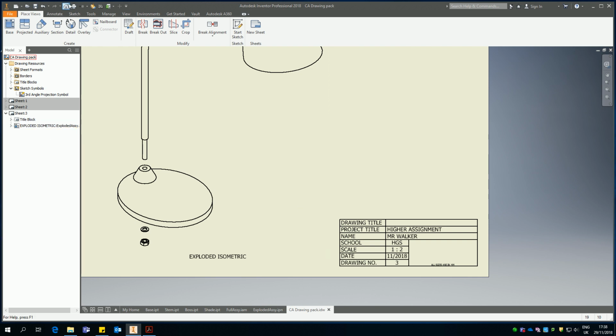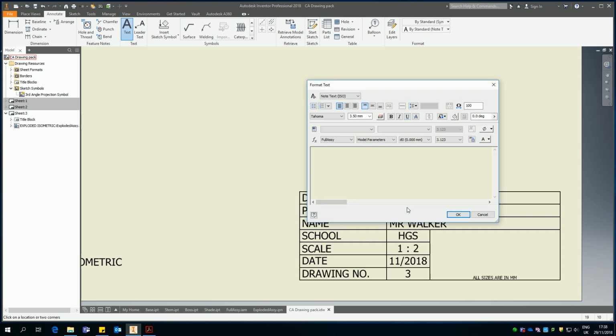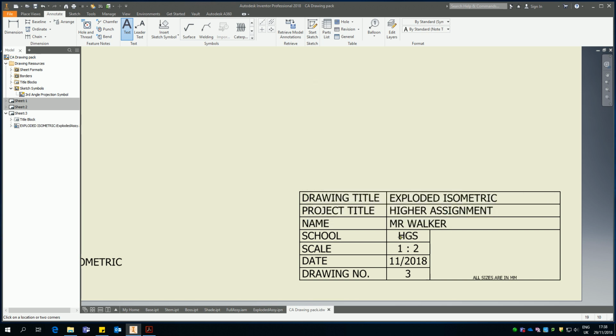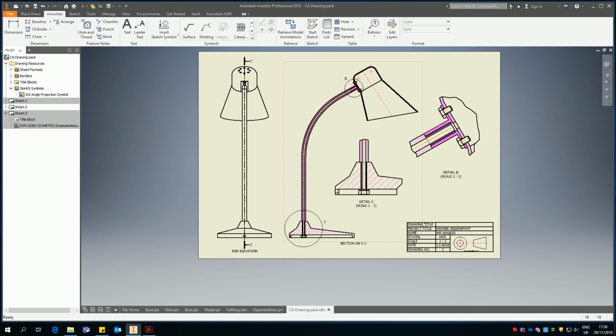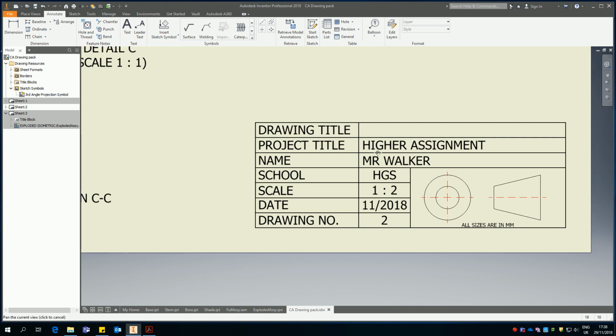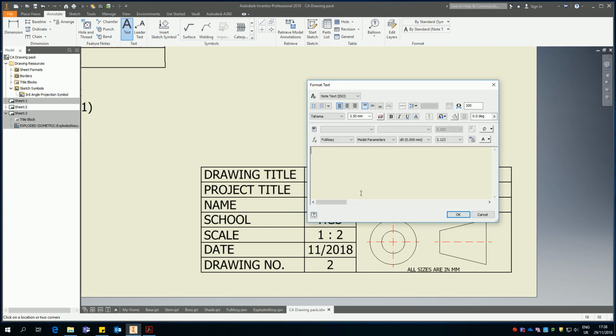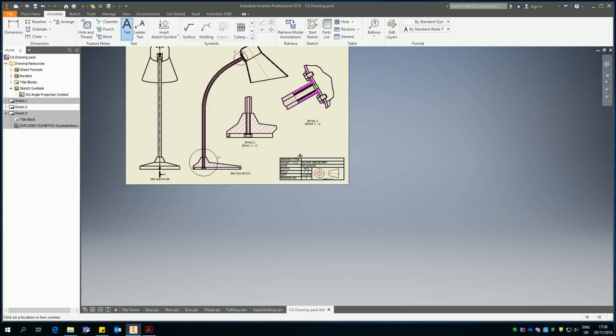The last thing that I want to do is add in the drawings or the drawing names. Same thing, we'll update this. If everything's gone right with the way they made your template, a lot of this stuff should be updated. Obviously you don't need to change your name unless you've had a change of name. And the drawing title for this, what's actually on this sheet, let's have a wee look.